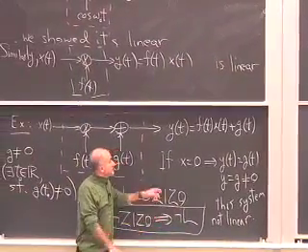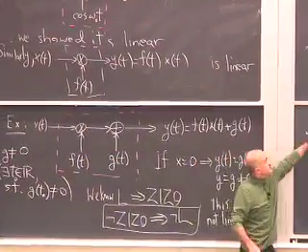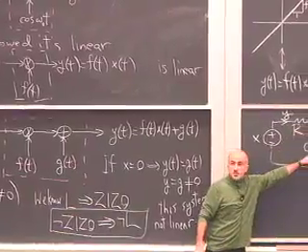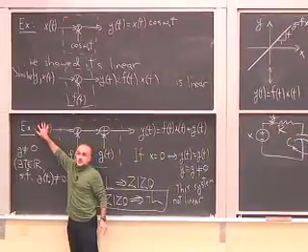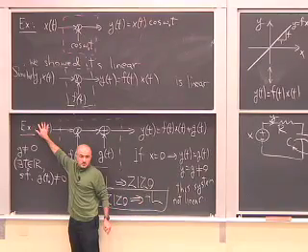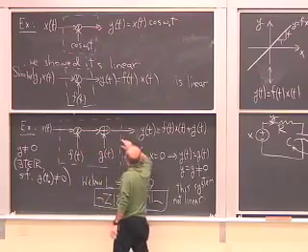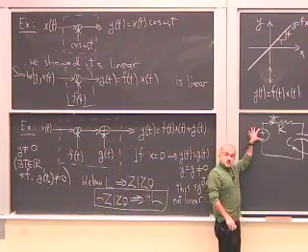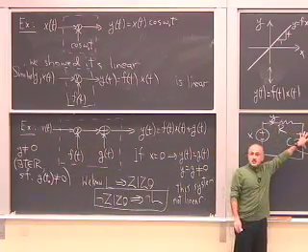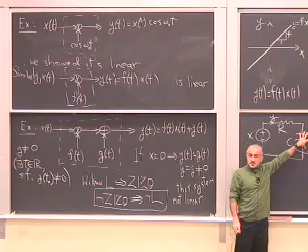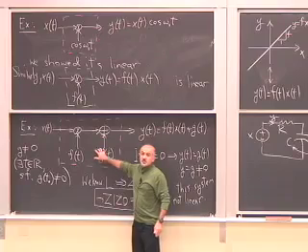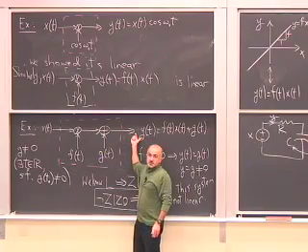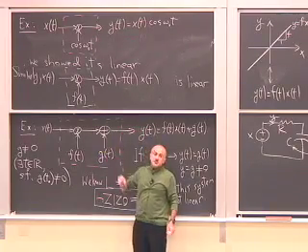So if I want to find the portion of the current Y, the output, that's only due to the capacitor and not the voltage source, I set the voltage source to 0. What do I get at the output? G. Now, you want to find the contribution just from the voltage source, so you assume that the capacitor is uncharged. So you set G equal to 0 and figure out what the response is. And then the overall total response will be the sum of the two.